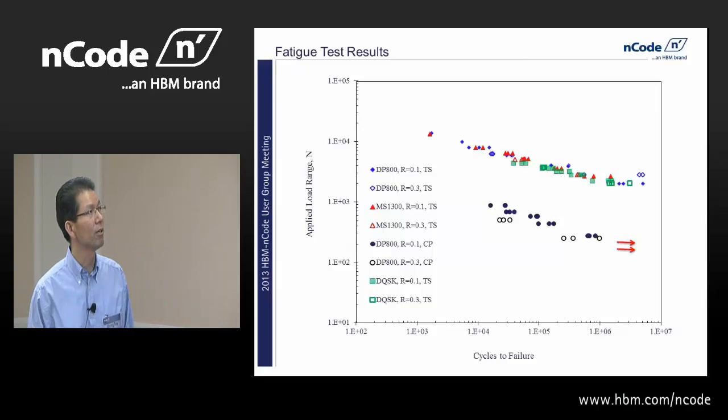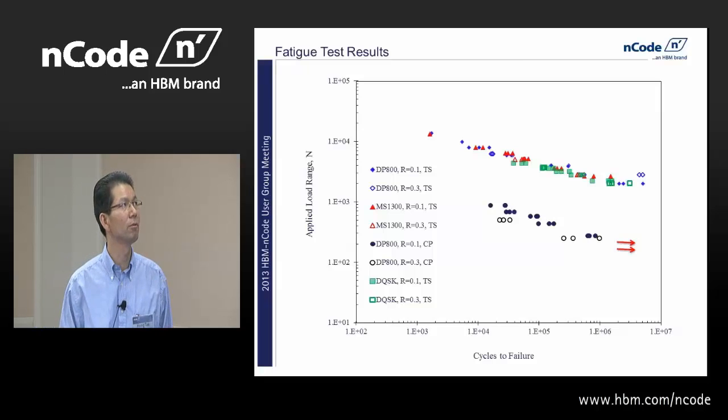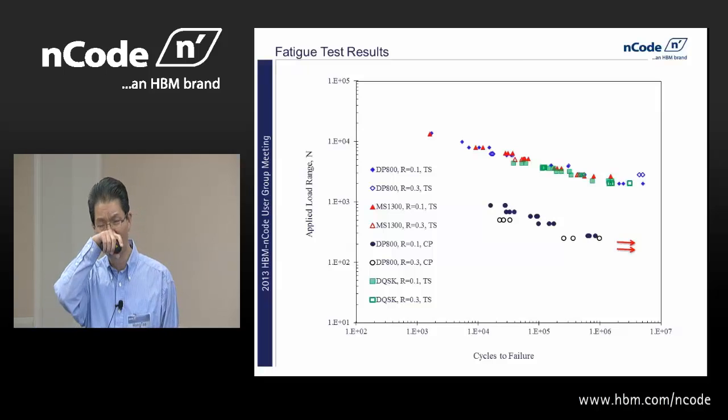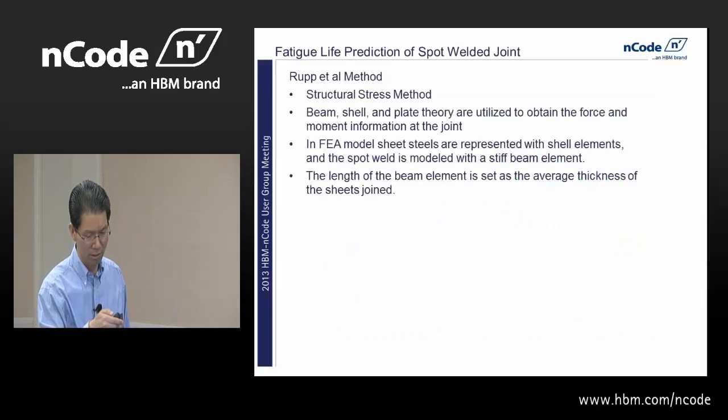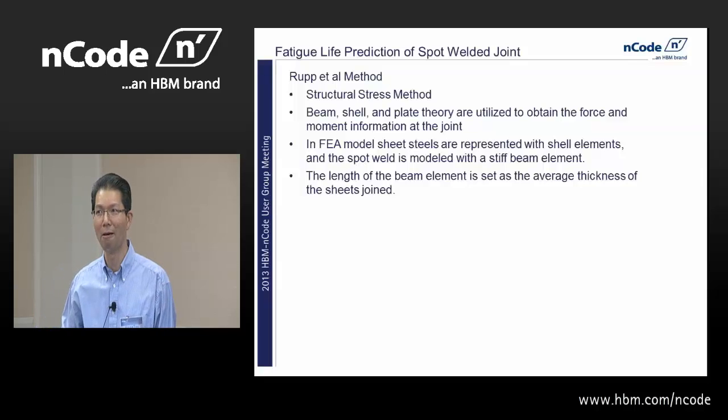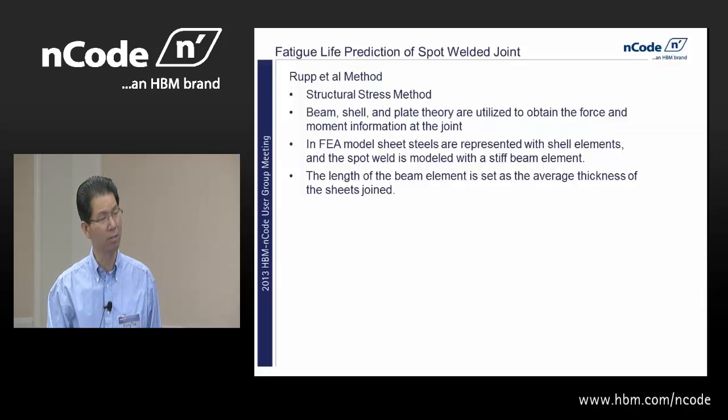Basically, for the structure stress method, we use the root method, which I believe is what the code uses. There's a slight difference there, but the basic approach is the same. We use that one because we have a design life, so it'll be a lot easier. Whatever structure stress method you're using, I think the same approach to modifying the SN curve works.